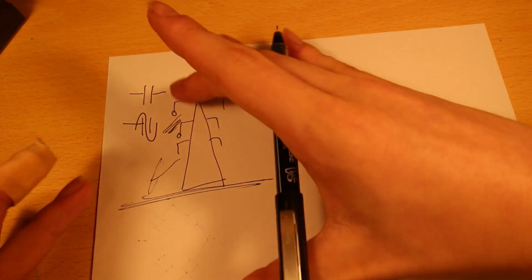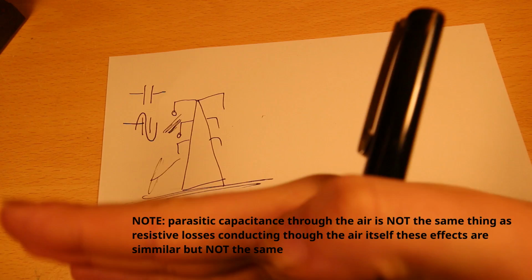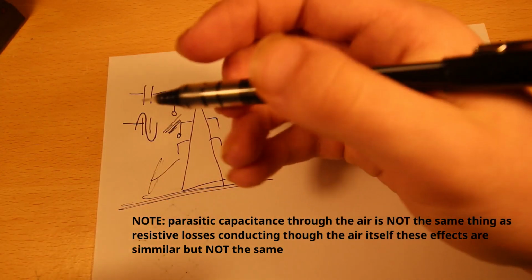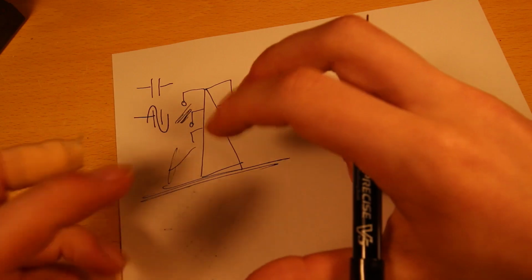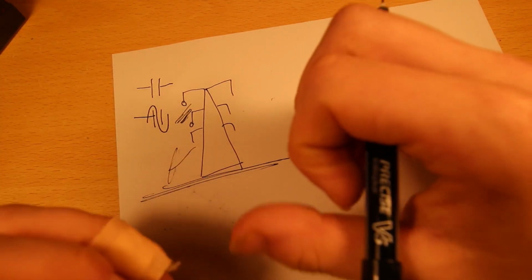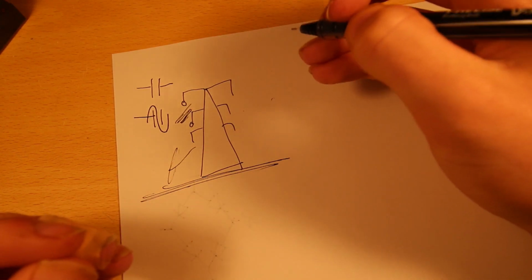So all of these capacitances, over short distances, they don't matter. Over much longer distances, they become really quite significant. And they can cause a fairly substantial amount of losses because current will leak through those. They're called parasitic capacitances. Like, they're parasites. They steal current from where we don't want it to go. You also get parasitic inductances.